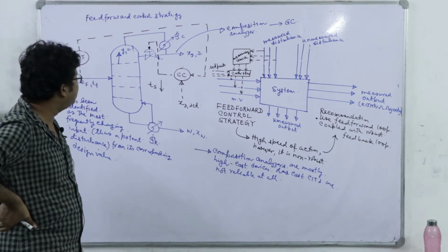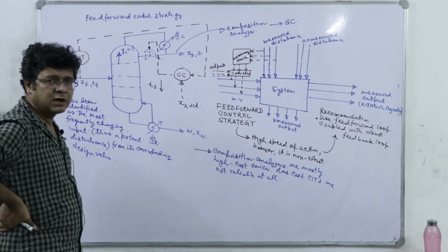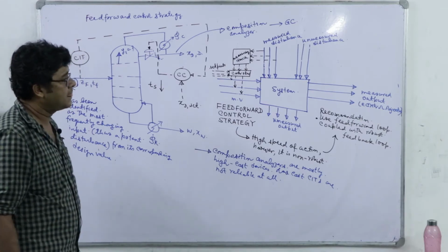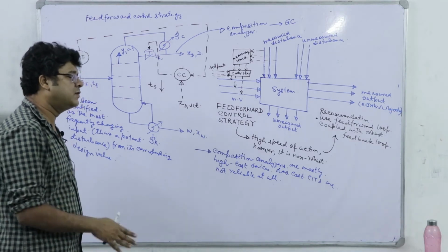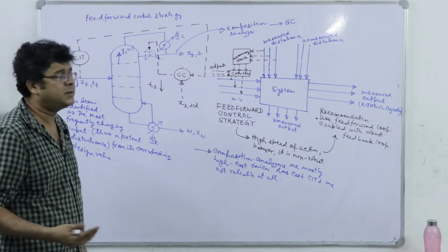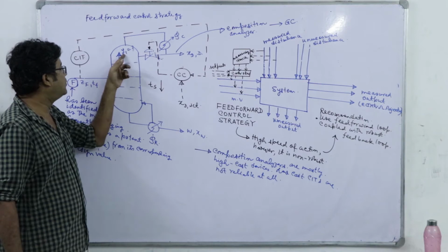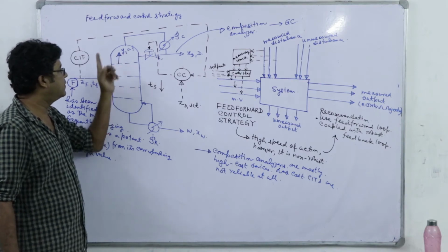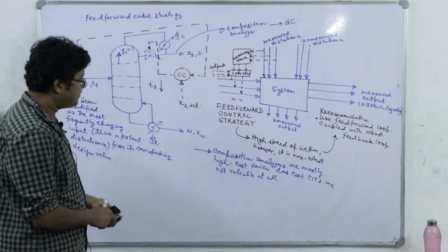We will measure the individual tray temperatures of that column, we will get a set, right. From there we will use the equilibrium relation, the material balance, the summability, and the enthalpy balance, and finally our output will be the vapor composition from the first tray. Okay.